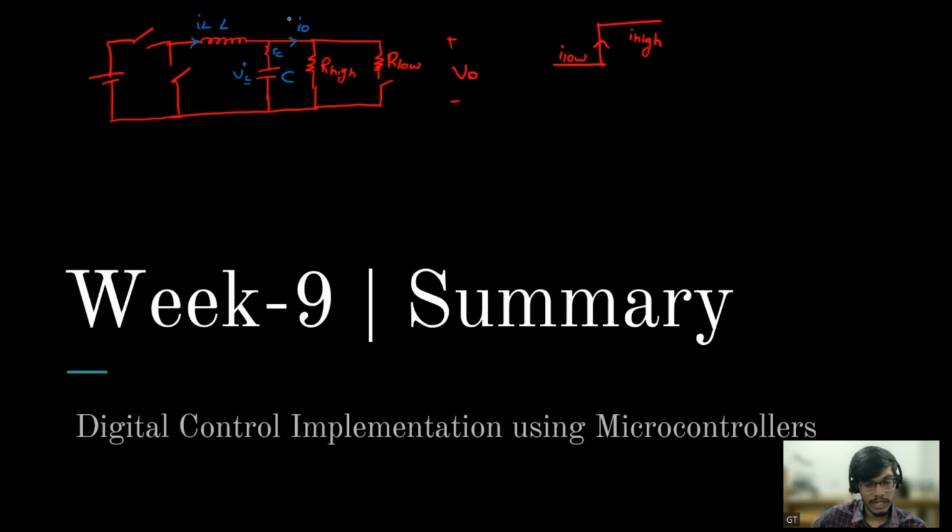So who will provide that current? If you see, KCL has to be followed, right? Say this is IC in the downward direction. So IL is equal to IC plus I naught. If IL is not able to provide, this current will be drawn from the capacitor. So this capacitor will provide that current, and as this extra current is being delivered, there will be a voltage drop across this RC.